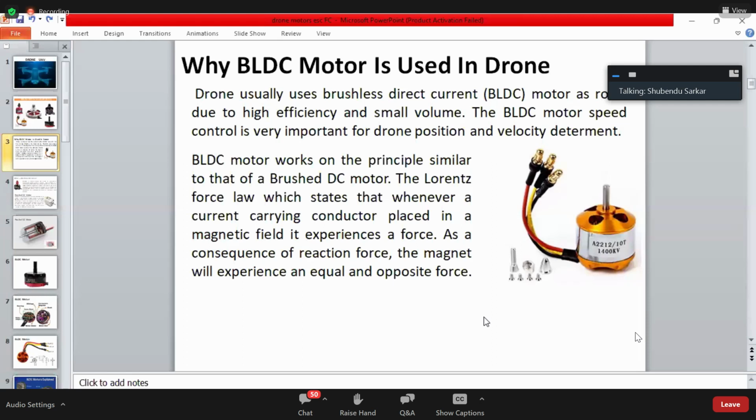What are the factors? Wind is the first. The weight of the drone itself, the vibration caused by these motors and propellers. So these factors are already present. Or for example, if you put a finger on the drone or push the drone like this. If I'm talking about wind, the wind is continuously trying to push the drone, and the drone is trying to hold its position and stay in the same place. So it constantly changes all the motor RPMs so that it can stabilize in a certain position.